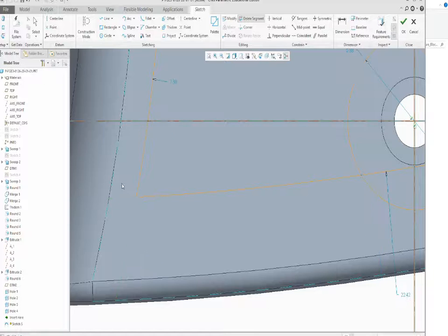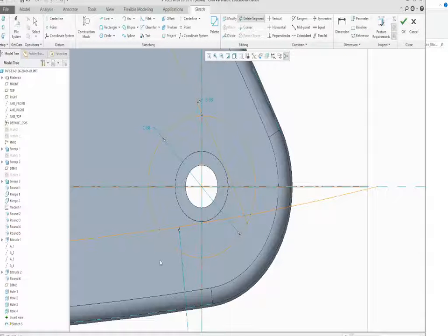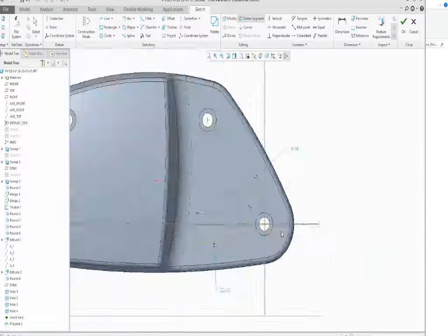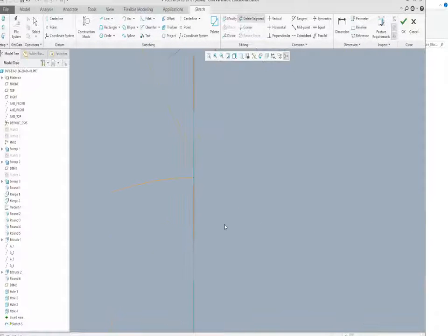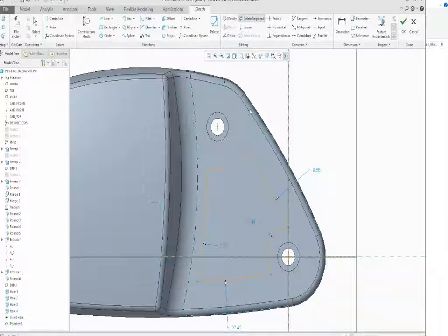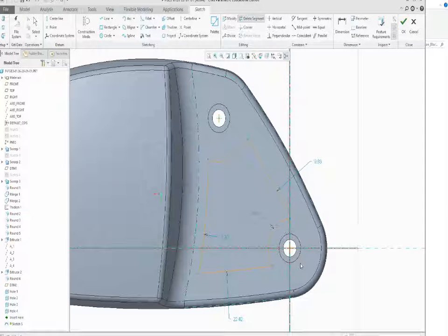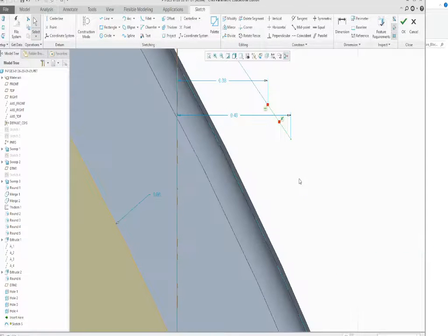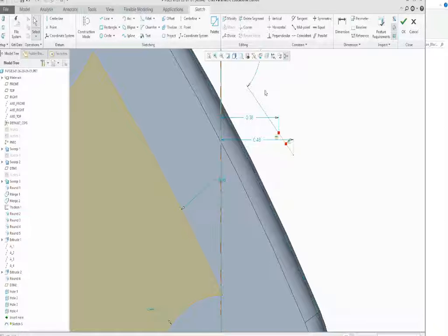Right here I'm going to start to work in on the edge. Here, start to work in on this edge. Start scribbling over here. Get all of these triangles out. And then right there, it looks like it comes down to a point, so it looks good. And this is to a point. If I'm at the point where I don't know if there's anything left, I touch the arrow. When it touches the arrow, it shades it in. If there was something left, like that, watch what happens. When I hit it, there's a red mark that pops up. So it's telling me, get this out of there. So hit it and delete.